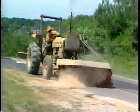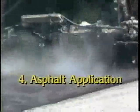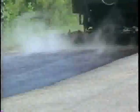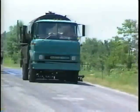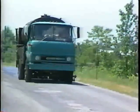Step 3. Clean the surface. Remove all loose material from the pavement surface prior to the seal application. A tractor-mounted broom is effective in removing most loose debris from the pavement surface. Step 4. Asphalt application. The asphalt application is the most important part of a chip seal operation. Emulsified asphalt is recommended. The asphalt distributor is set up for the proper application rate. Monitor the application for proper application rate to prevent streaking.